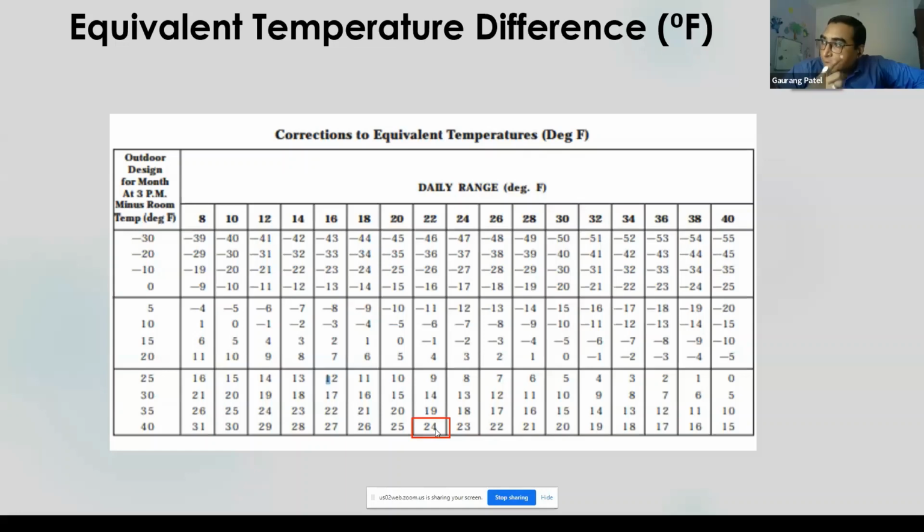See, if you are adding anything ahead of your wall, for example, I have a west wall and you add something to shade that west wall, then that wall acts as a north wall, because north does not have any direct sunlight. The north wall is always considered a shaded wall. So if you put anything additional as shading, like solar panels, and cover that west wall with them, you need to consider that west wall as a north wall because it is a shaded wall.